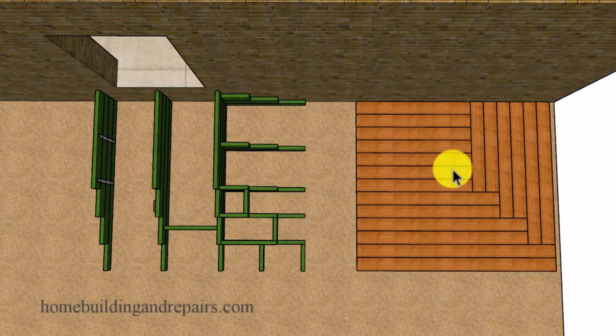For example, if I had 10-foot 2x6, I could lay the 10-foot 2x6 next to each other, put the desired gap in between each board if I'm going to have a gap in between each board, and then grab my measuring tape and measure the distance. And if I want to make this distance here the same as this distance here, so that both the width and the length or the depth of the deck will be the same size, then I can do that. And it wouldn't be that difficult to lay out your boards in this direction here with the desired gaps if you're going to have them, and have them run full length to get these measurements here.